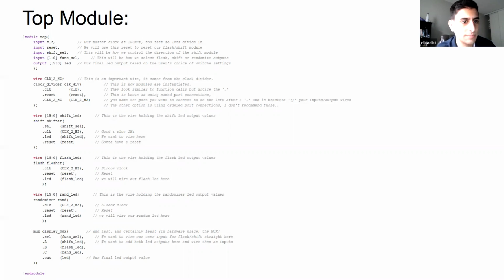Just the dot part. You still want your input to be clock, but right after the dot you want clock 5 megahertz. The dot signifies which input you're trying to target with the assignment. Sorry about that, guys.